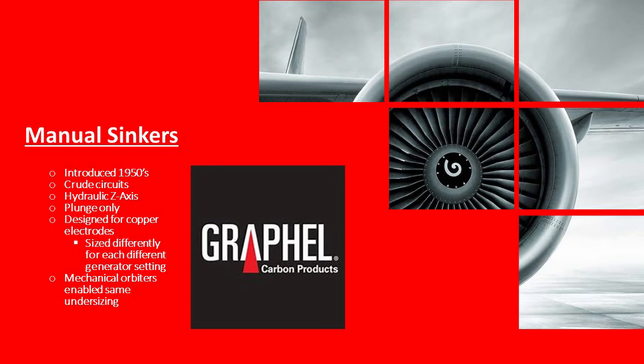Electrodes back then were all sized differently for each different finish that you were going to achieve with that electrode. So in other words, you would have 5 different electrodes to go from your rough to your final finish, but each one would be undersized differently for the different power settings because you didn't have that orbiting capability.